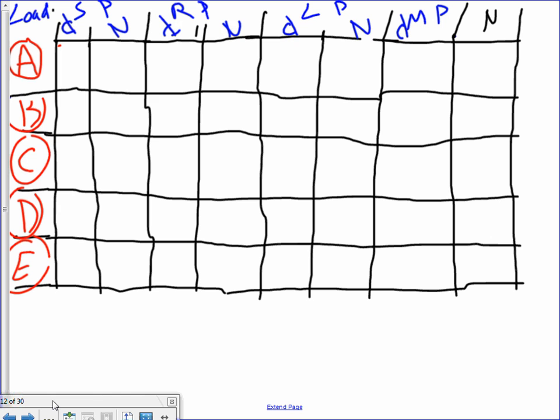All right, you guys have this sheet in front of you. I'm going to fill this sheet, and I'm going to tell you why. Everybody has this sheet, right? Now, let me walk you through what this sheet means. This is for all the A, B, C, D, E steps that we did, which is basically the receptacle, lighting, heating, cooling, motors, and kitchen equipment. 5 types of loads. How are these 5 types of load going to fit under the service panel, the receptacle panel, the lighting panel, mechanical panel? You guys have 3 of them in your sheet, instead of 4.